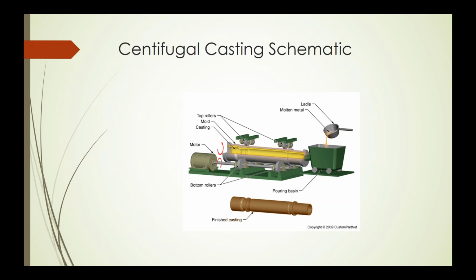The RPMs of the mold are based upon past practice. Then it's cooled. As it's cooled, the part is formed or solidified into shape. And obviously, the casting mold is machined very carefully to produce whatever shape the final customer wants, save for some final minor machining.